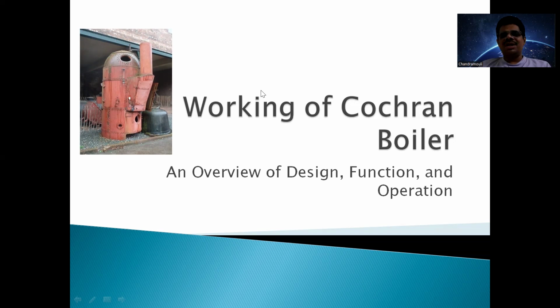And there are different types of boilers based on different criteria, like based on the content inside the tubes. Boilers can be classified into fire tube boilers and water tube boilers. If the flue gases or hot gases flow through the pipes and water surrounds the pipes which carry hot gases, then such boilers are known as fire tube boilers. And if water is flowing through the pipes and hot gases surround these pipes, then it is called a water tube boiler. We shall see the comparison or the differences between these two types of boilers later in this session.